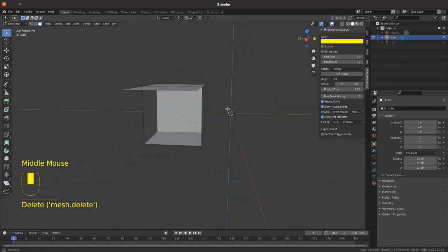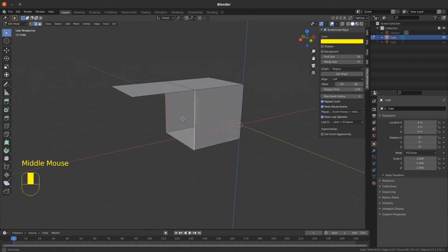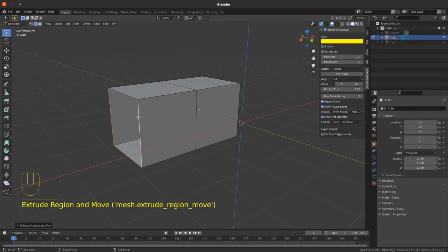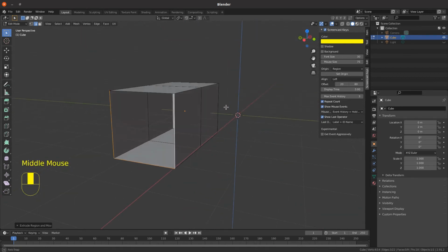So I'll select the internal face, and that can be deleted by selecting faces from the delete menu. So that opens the original cube up, and we can then go back into edge select and select the 3 faces that haven't been extruded out so far, and extrude those on the -X axis. So we press E for extrude, X for the axis, and then -2. Enter. So we've now got what looks like a box with an open end, but you've actually got